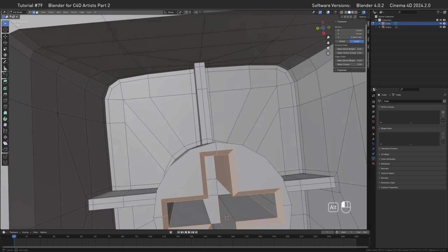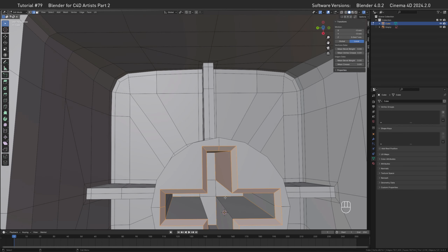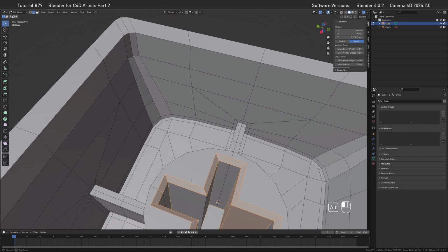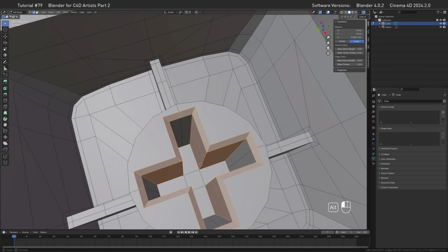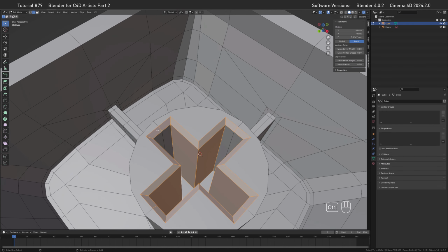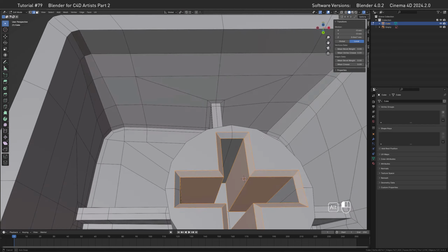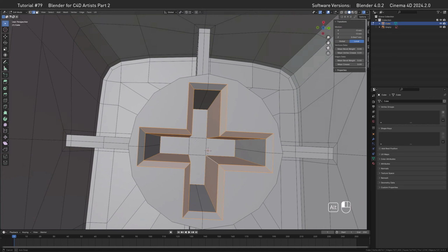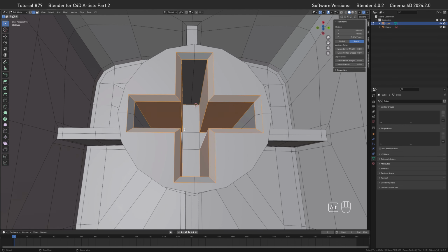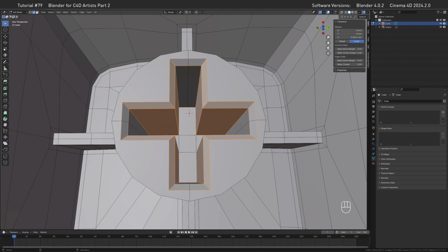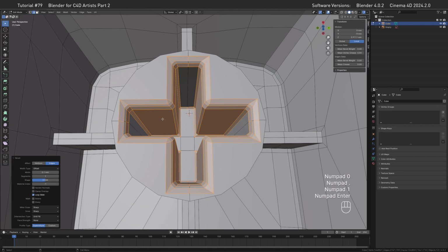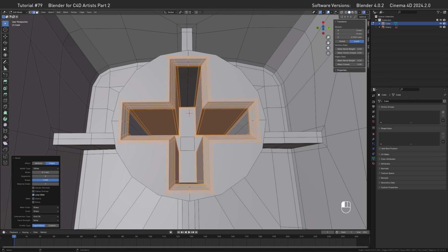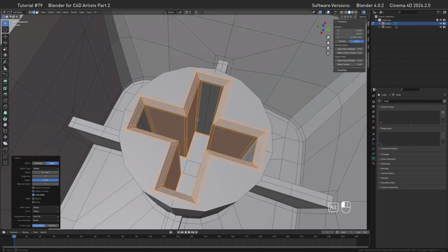Those are the tedious parts of modeling usually. So here we go. That looks alright. Also deselect those edges since we don't want to bevel them. Here we go. And then let's see if we selected everything as intended by beveling them. Again, B 0.1 or something like that. Then what we want to do again is go with the segments of 2, the shape of 1, so we have the solid bevel here.